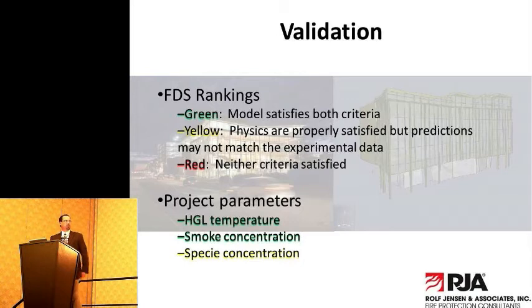FDS is definitely applicable and an appropriate model to be looking at the transport of smoke through adjoining spaces, and that's what the comparison of the measured data to the predictions showed. And for species concentrations, however, actually I believe species concentration should be green. I apologize. I think I messed up those colors. I know I did, because smoke concentration is the yellow one ultimately.